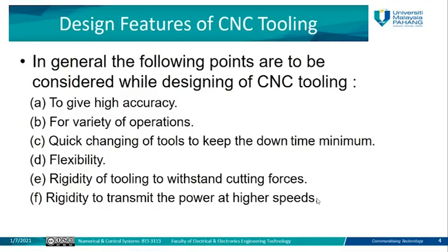Also flexibility, rigidity to withstand the cutting force, and rigidity in transmitting power at higher speed from the spindle to the cutting tool and the workpiece. All these features should be considered during the design of tooling for CNC machines.